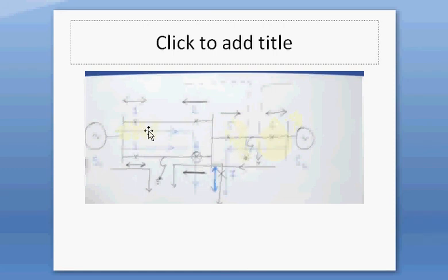Now relay at position 2, again the direction of current for feeding the fault is still the same, therefore 2 will not operate. And 1, again the direction of current is like this and it is a non-directional relay, but the value now exceeds the pickup value of relay 1, that's why relay 1 will also operate. So for relay 4 the backup relays are relay 6 and relay 1.